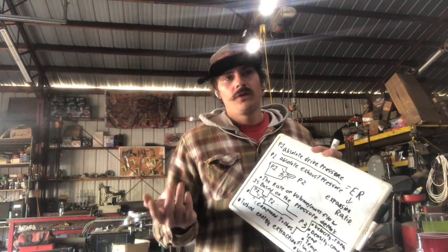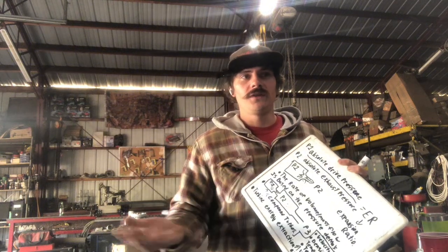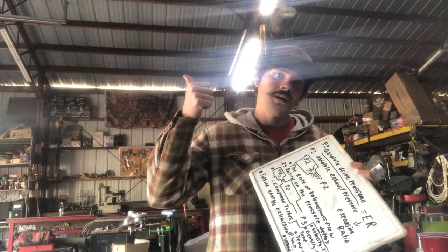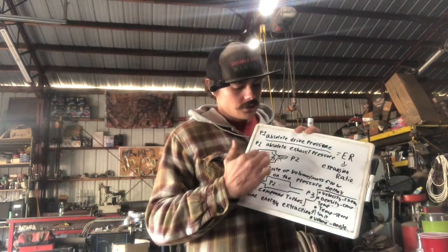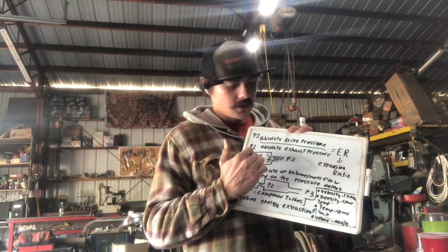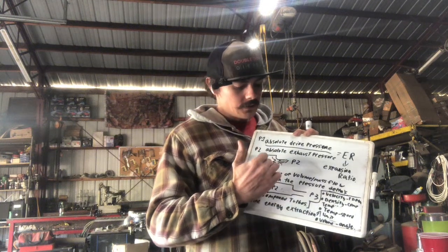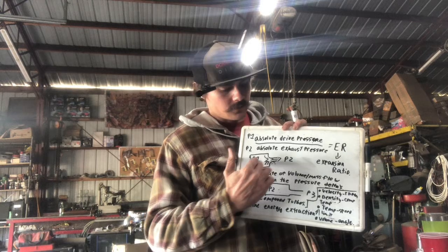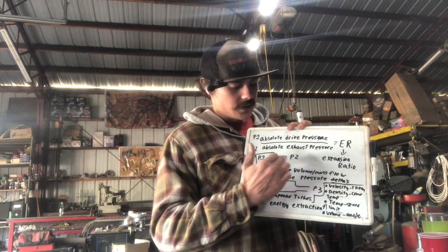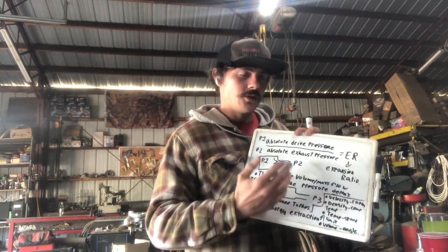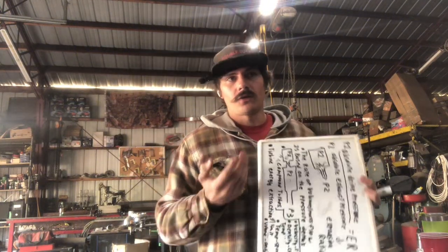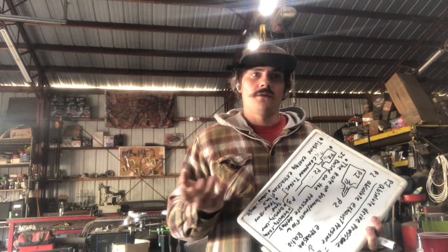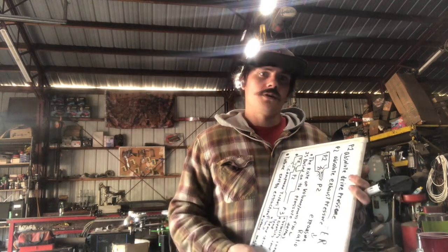On a compressor, you were positively putting air somewhere where it can't go anywhere else, so the pressure ratio can be really high. On the exhaust side, we are only moving exhaust gas through pressure deltas. So the rate at which it can move from the manifold to atmosphere is governed by the speed of sound through the nozzle. Because we can't go faster than the speed of sound through the nozzle, it just so happens that the speed of sound through the nozzle generally occurs at around the 3.0 expansion ratio.